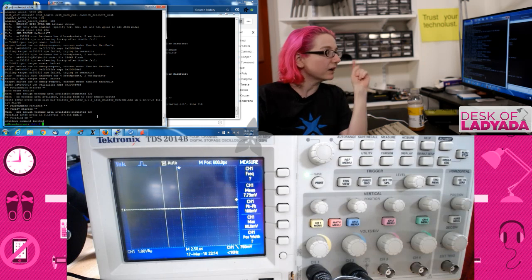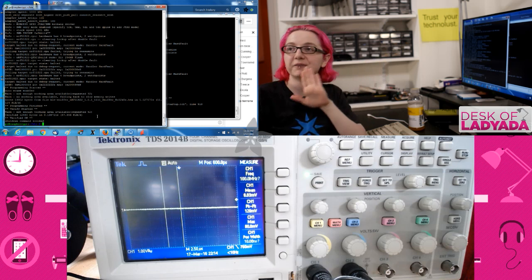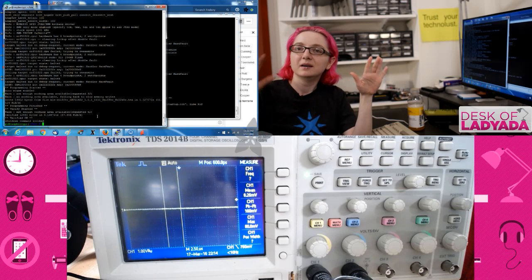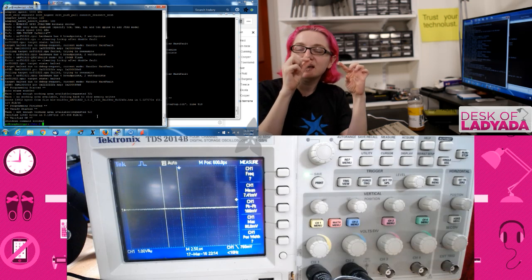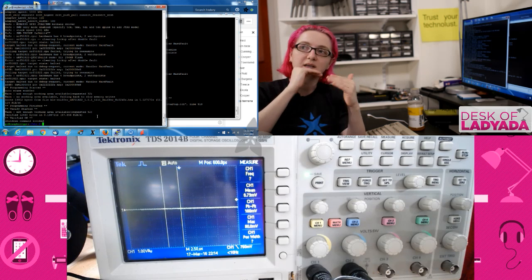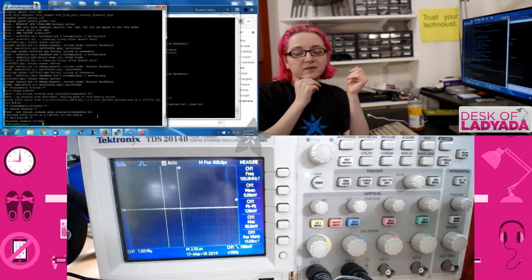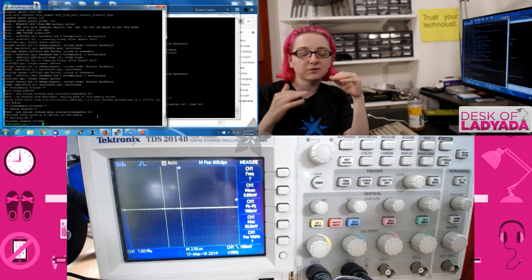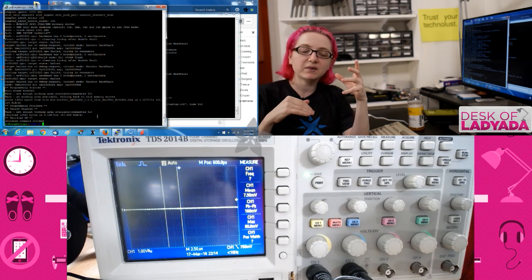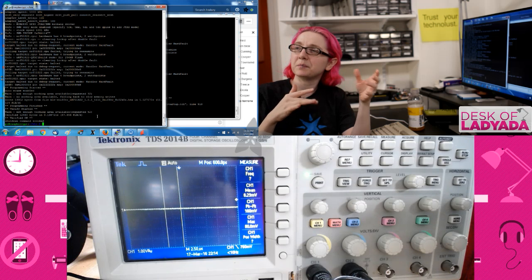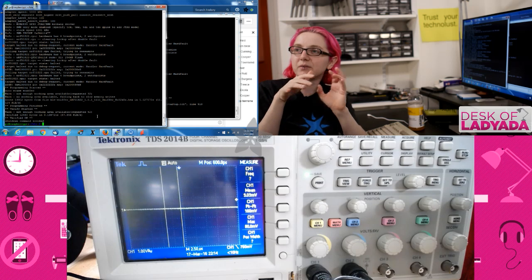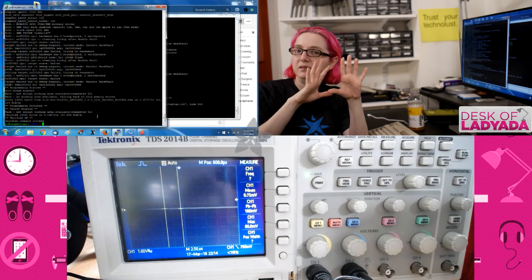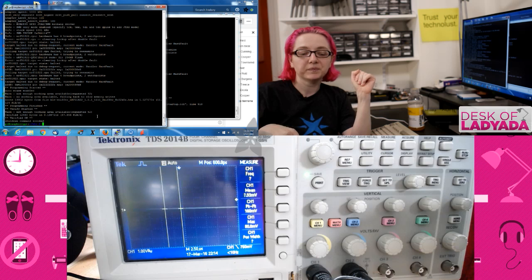So yeah, the Nordic, I spent a couple hours and I totally found these magic commands in exactly this order, and it has to be reset, halt, not reset, halt, and then you mass erase and then reset. The SAMD21, I'm still kind of figuring out, like sometimes having the reset line connected helps and sometimes it doesn't. So I might have to add delays or whatever just to figure out this path that will let me consistently program them.